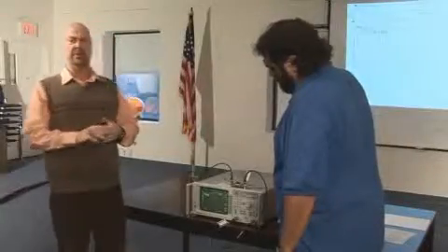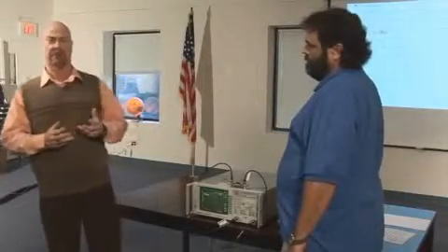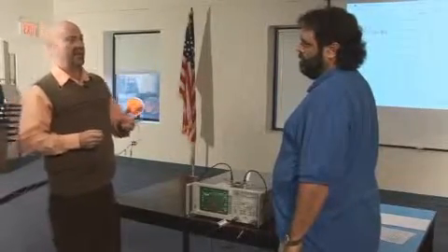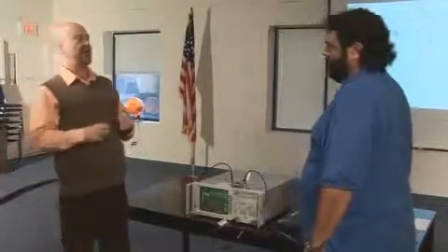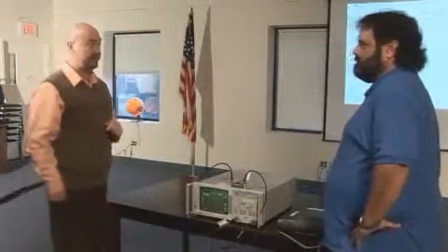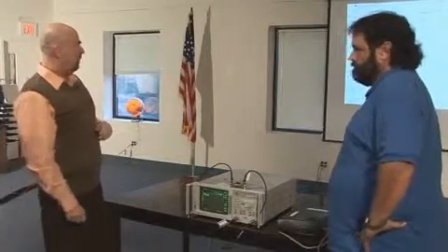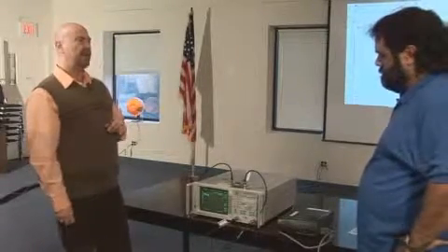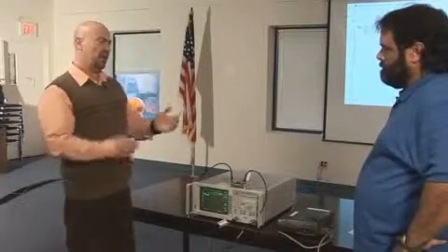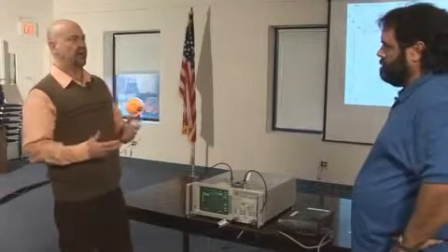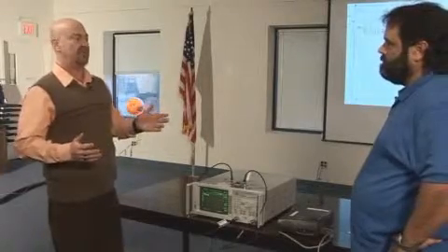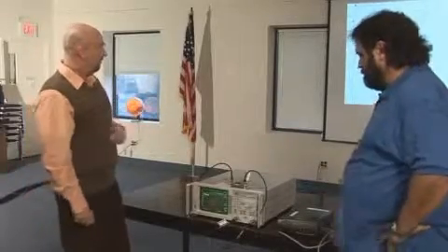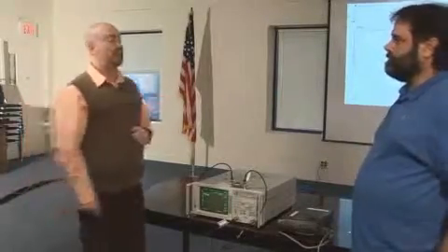Typically for filtering, these are used only in lower frequency ranges. At the higher frequencies, you end up with problems because of stray capacitance that forms in between the windings of the inductors. So this is just showing that you have to be wary when you use these devices. You really have to know what frequencies you want. And if you prepare early, your mechanical engineer or designer should leave traces on highly susceptible signal lines for you to put surface mount type devices on. And if you're careful, you can make this work in trying to get fixes.